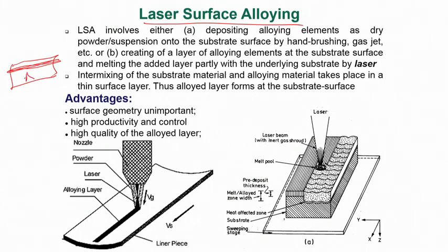If this is underlying substrate A, then this top layer could be A alloyed with element B, or B can be anything like a single element, or it can be a compound. So in the process, we can create a microstructure which is not just a solid solution, but can be a two-phase or multi-phase aggregate, including dispersion of certain intermetallic phases and so on.